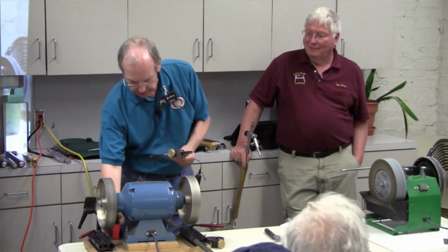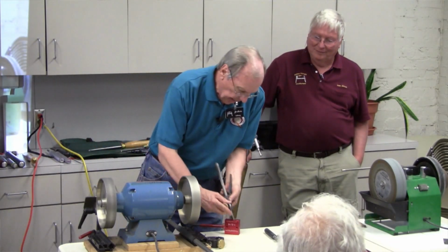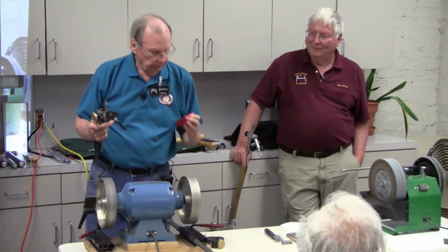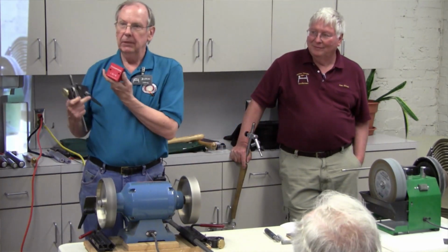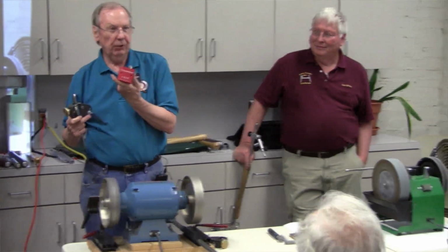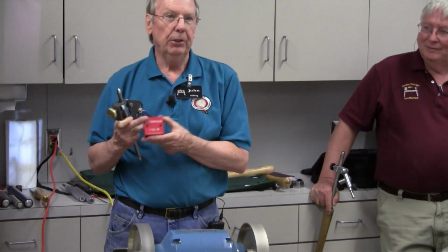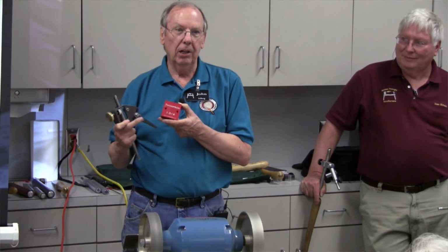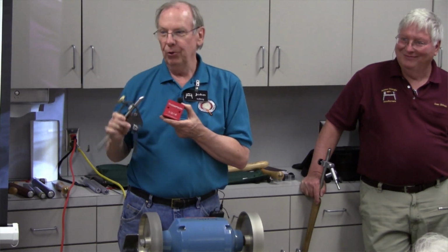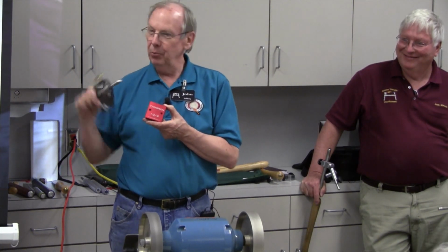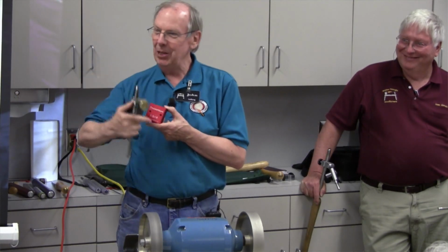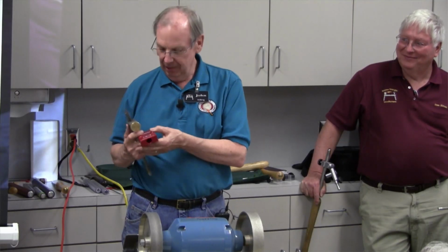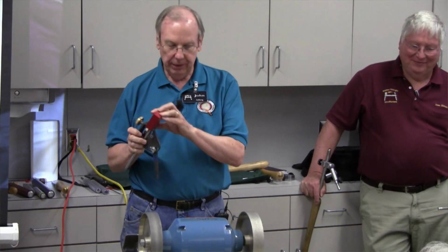Okay, we're going to do a bowl gouge now as well, and I use the Wolverine jig. I use a Thompson stick-out tool. I made my own out of a 2x4, and after I used it so long, it kept getting deeper and deeper. So if you make one out of a 2x4, put a nickel in the bottom of it so that it doesn't keep getting deeper and deeper. But this one was so cheap, and it's 1 3/4 deep, and so I use that to set the length.